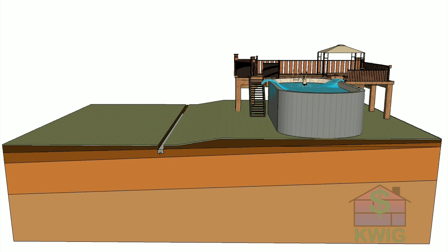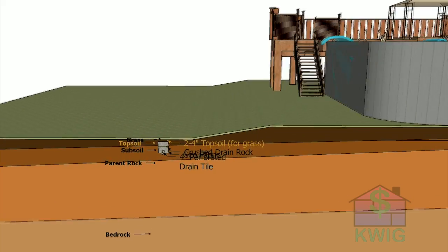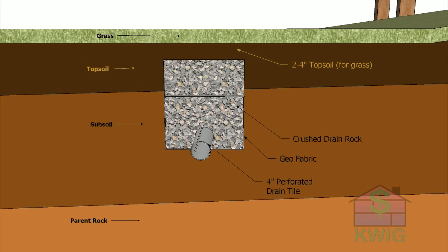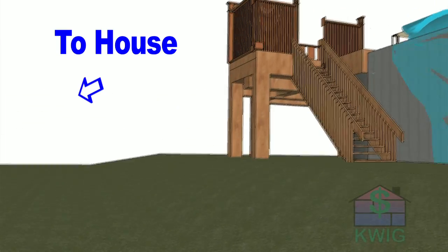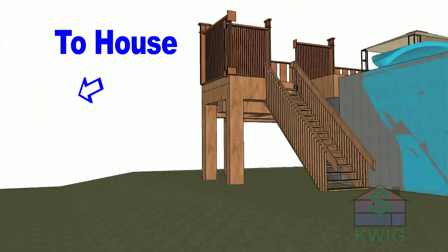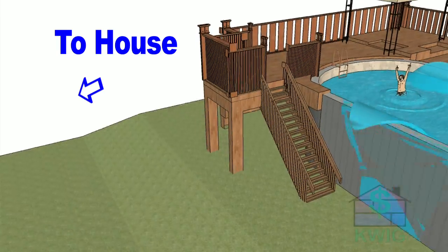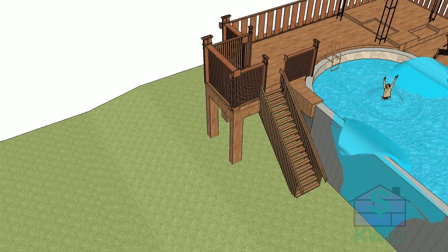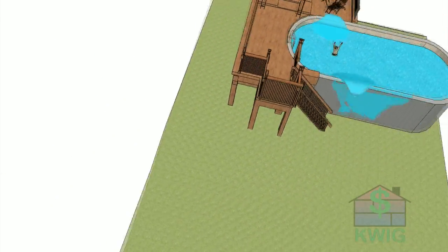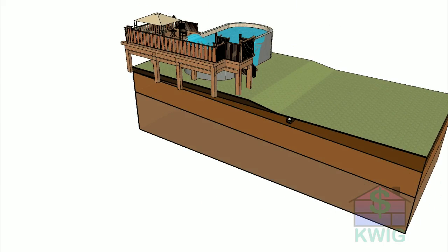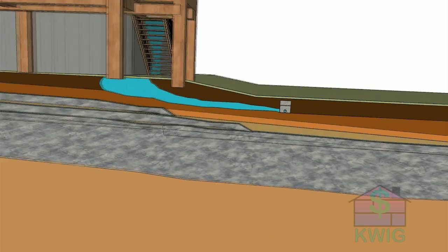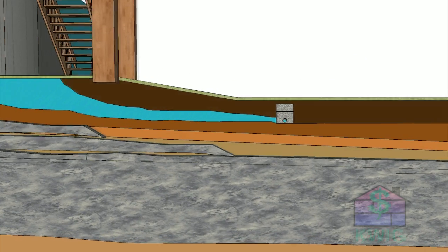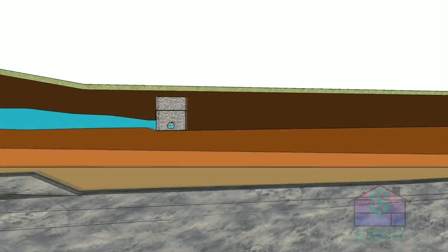French or curtain drains are good solutions for homes that are on even a small slope. These are generally placed a few yards uphill of the house and a foot or two below the surface of the yard. This will capture and divert the rainwater, snowmelt runoff, or other groundwater which travels mostly within the naturally loosened top 24 inches of the soil.